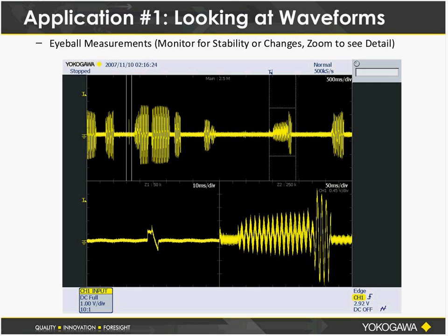Maybe it's a destructive test or something like that. Or maybe anyhow, it's a 5-second test. And then after that test is completed, we want to go in and stop it and analyze it in the instrument, maybe on the PC. And so on the bottom left and the bottom right, we see zoomed in sections where we can analyze the spike a little bit more closely, or we can analyze the noise there on the right-hand side a little bit more closely. So this is one typical type of waveform observation setup that you might use on an oscilloscope.